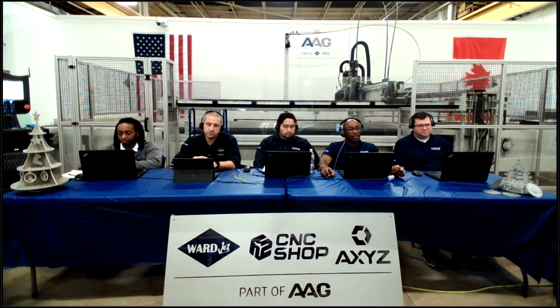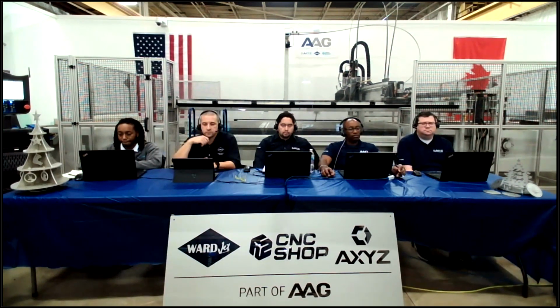One of the things that people do during the purchase process is get their water analyzed for hardness, and I've got charts that have the limits and such. Usually people get a water softener. If your water is so hard that you need a DI system, they'll set it up to blend in a little bit of untreated water, because you don't want to use absolute pure deionized water, which will attack the stainless in the intensifier and such. So by and large, water softener, if your water is incredibly hard, potentially deionization with a little bit of untreated water in there.